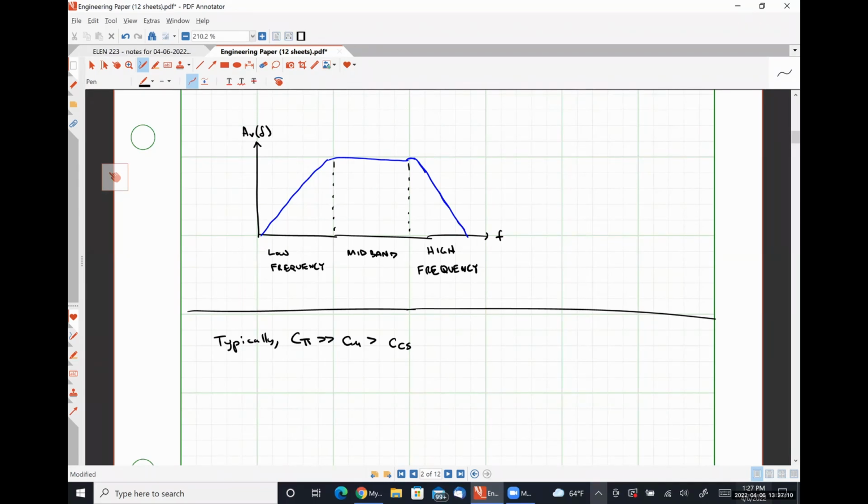I think one of the biggest reasons is because the values can vary so much from process run to process run. Let's say that the ion implantation of your base layer ran 10 seconds longer in one process than another. That means the thickness of your base is going to be slightly larger, which is going to change things by a pretty large amount.